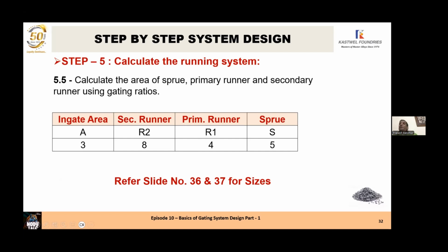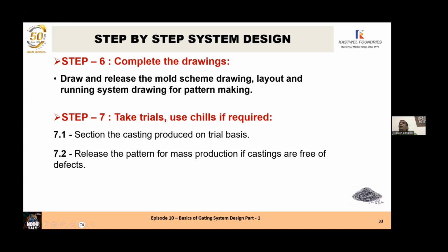Next slide, please. Draw and release the mold skin drawing, layout drawing, and running system drawing for pattern making. Take trials, use chills if required, section the casting produced on trial basis, and release the pattern for mass production if castings are free of defects.